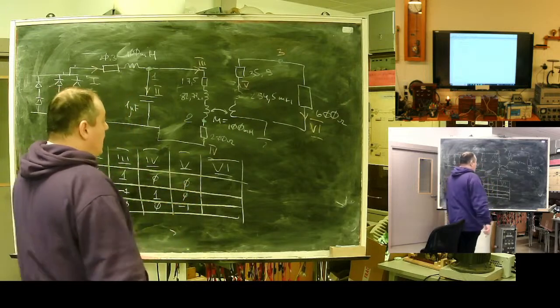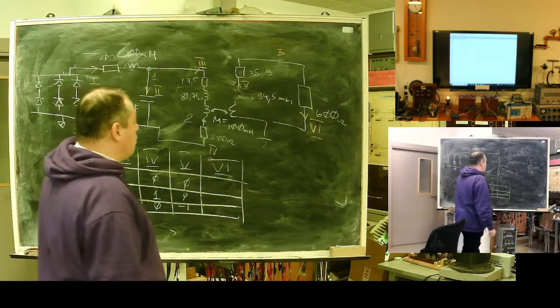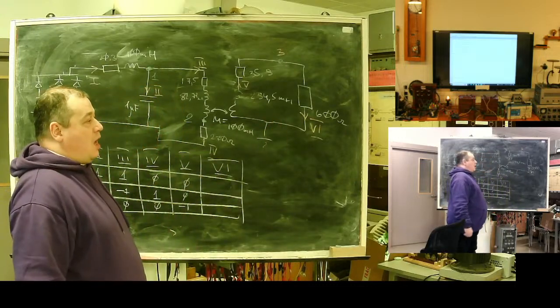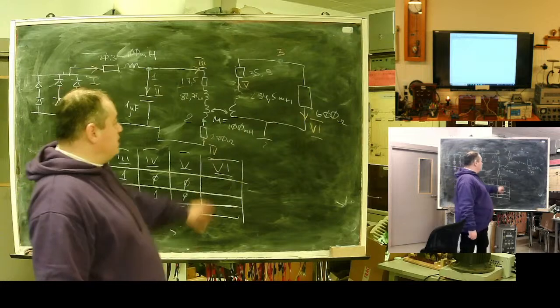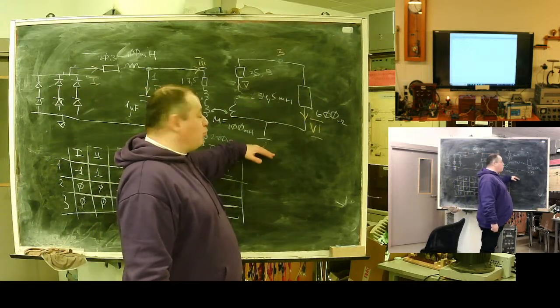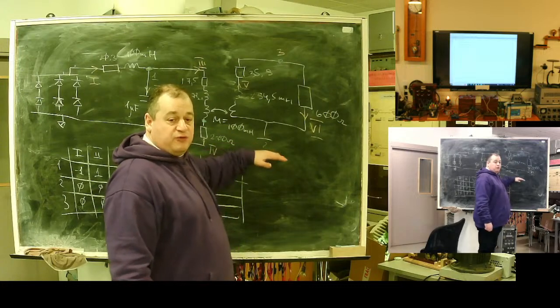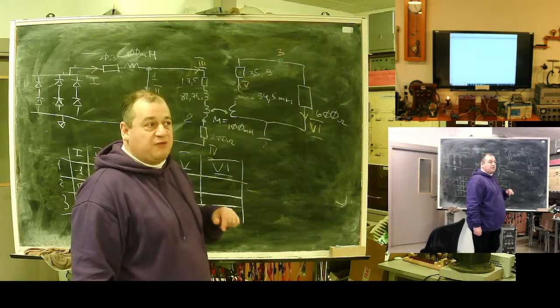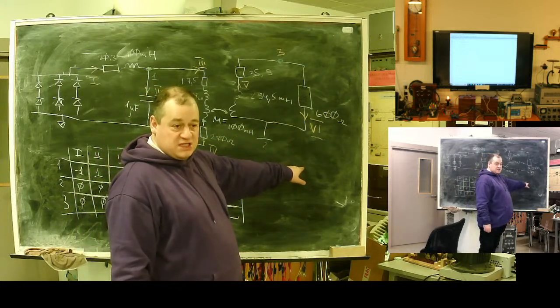One remark, I can solve only a network represented by a connected graph. So, in theory, this part is separate. I can put an earth point here. If not, we should create this ring artificially. We should add a large resistance.